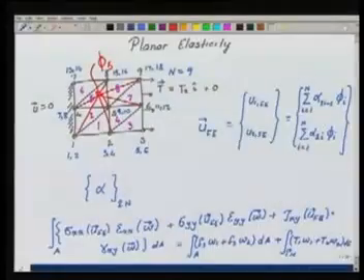So again, if I go back here, if I look at these elements, you see for element 1, I do nothing on any of these three edges, because on these three edges either zero traction condition is given or no boundary condition, or these are internal edges. If I go to element 2, here the displacement is 0 on the third edge of the element 2, on this edge of the element 2. So as far as this element is concerned, again I do nothing as far as the integrals on the boundary is concerned.